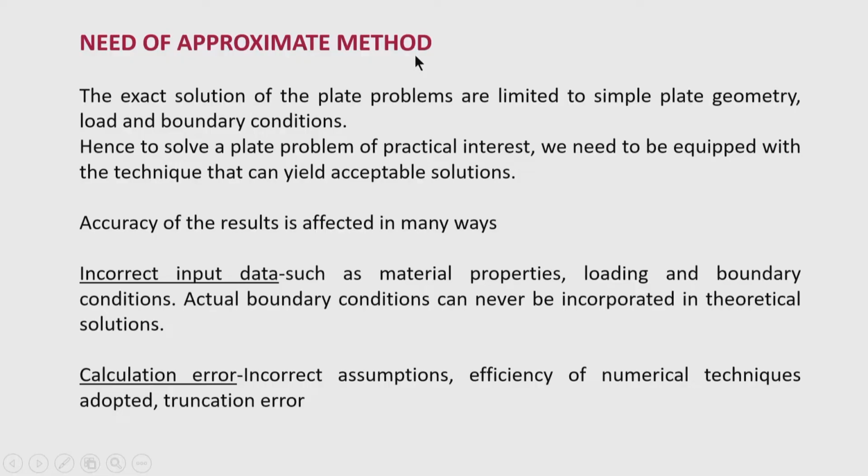Also, you have seen that the loading condition plays an important role, because if the loading is unsymmetrical, then we could not find the solutions of the circular plate using the axisymmetrical condition for the differential equation. So, some techniques are required to be developed for solving problems which are different from the conditions encountered in exact methods.